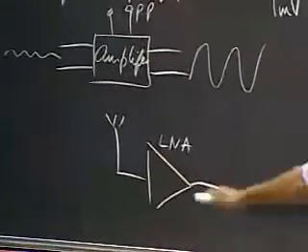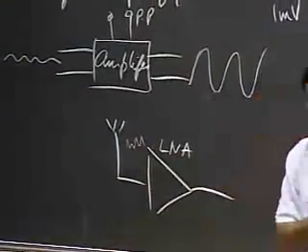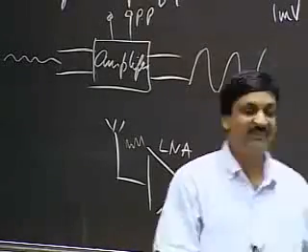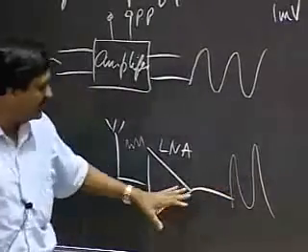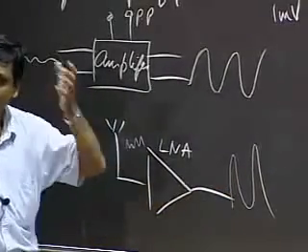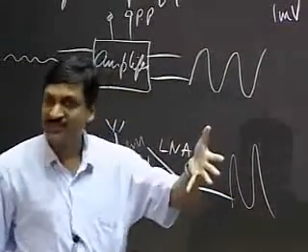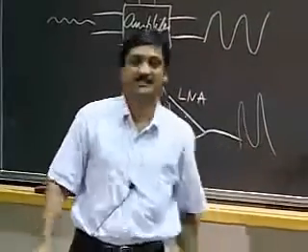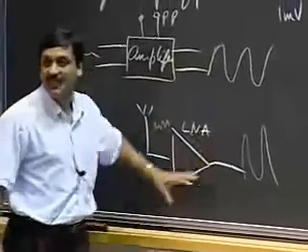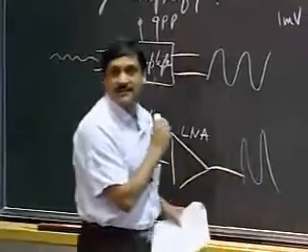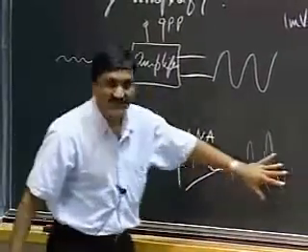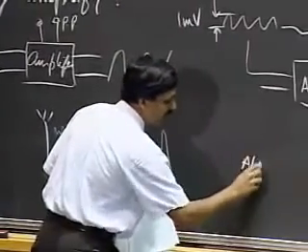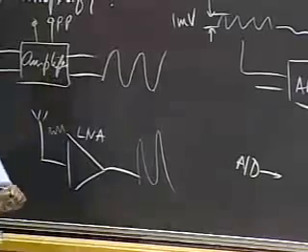So I get a really rinky-dinky small signal here, and then the low noise amplifier amplifies the signal. And in real cell phones, and for that matter, in your 802.11b or 802.11a or 802.11g wireless cards, same thing: antenna, low noise amplifier, and then you may have a bunch of processing. Commonly you have a bunch of analog processing, and then you convert the analog to a digital signal.